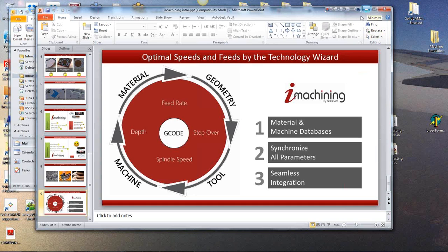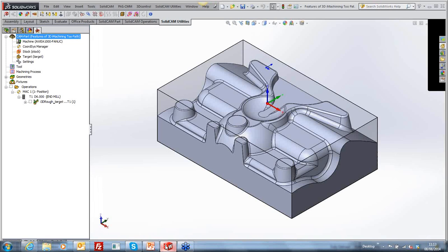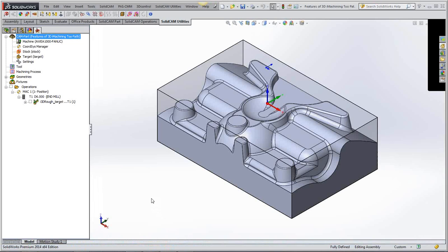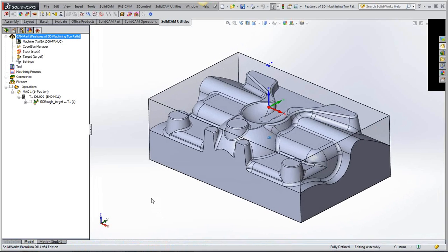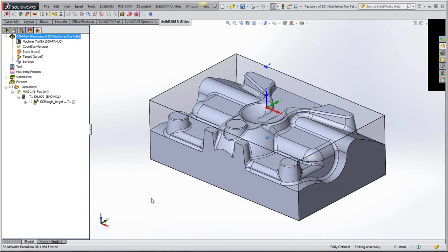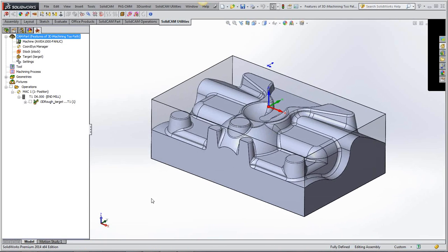Let's just do that on a model here. What I've got is a simple little mold tool, it looks like, doesn't it? And I know you would normally use a tool steel, in EN19, EN24 type of steel maybe, something even harder than that, like a D2 or something, steel for a mold. But for this demonstration, this particular part is made out of aluminium.